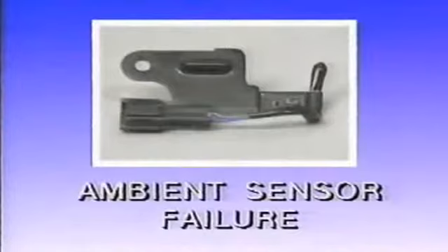After these areas have been proven to operate properly, the chart leads to the harness test. Each step should be followed carefully to avoid false readings. To demonstrate some typical troubleshooting procedures, 4 examples will be presented. Ambient sensor failure, 2 types of actuator failures, and a no cooling complaint with the compressor engaged.